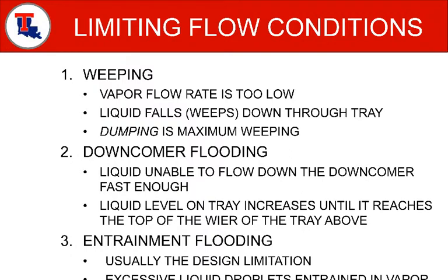All right. Let's talk about a few conditions that often happen in a tray tower. One of them is weeping. So what is weeping? Drops are falling. Drops are falling from where? Well, drops could fall through the seals of the trays.